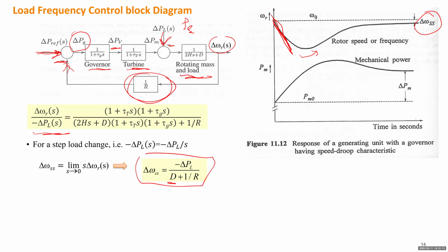So in order for this control to function, the deviation has to be non-zero. So it will never eliminate the deviation. In order to get rid of the frequency deviation, you have to introduce another type of controller that behaves like an integral controller. An integral controller will integrate the effect of the deviation accumulatively, and finally it can eliminate that error.